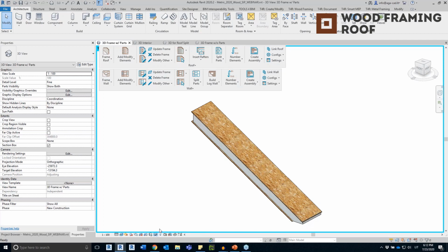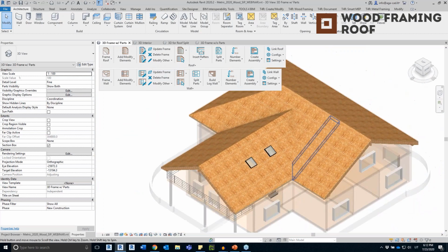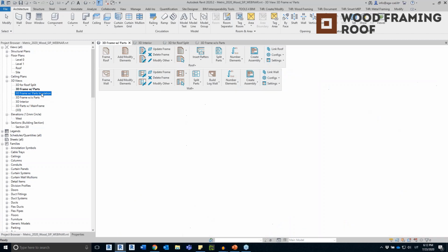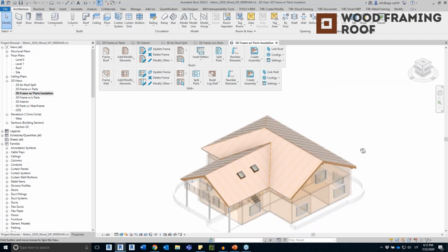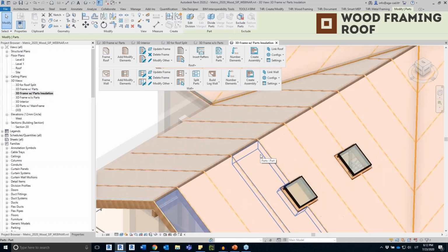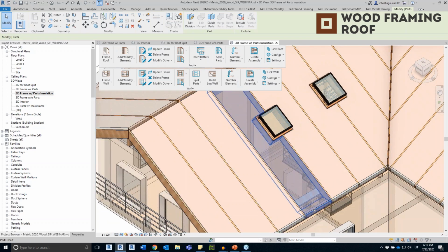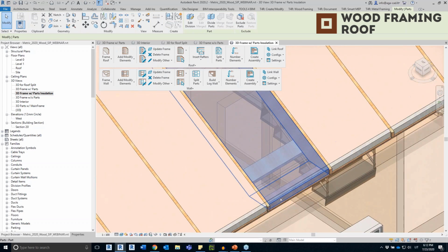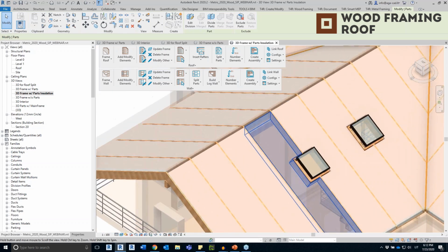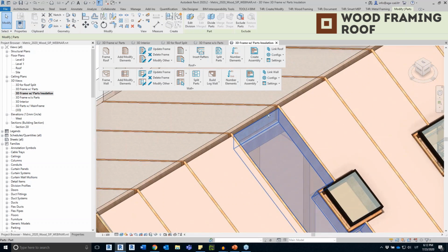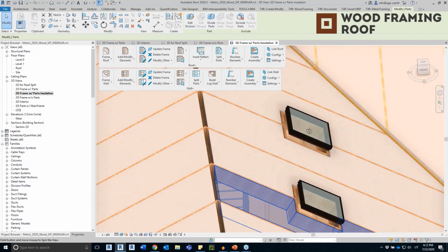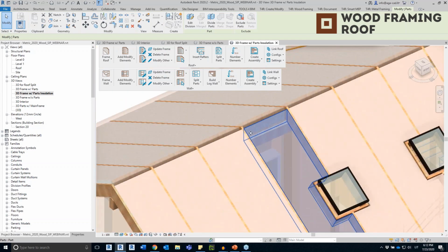Okay, now I will reset this mode and I will go to another view that filters only the insulation part. And actually, I want to frame these parts as well because I want to add trimmers on the bottom and on the top of my panel. You can see I have a space here where they will be added.